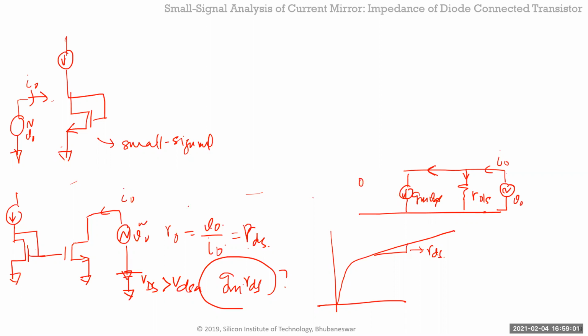Yeah, but when I'm measuring this, there is no small signal voltage on the gate. You remember how we created the small signal model, right? All independent sources, 0, DC sources. So in VGS, there should be only the DC voltage, which means that's grounded, right? So that is grounded, which means there's no small signal gain here. This is 0, which means there's no current here. So V out by I out is just RDS, right? So just your output impedance of this thing.